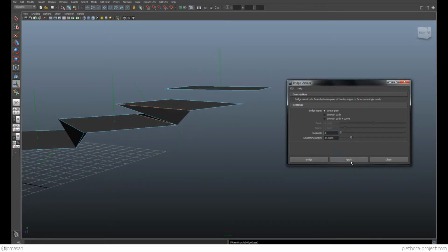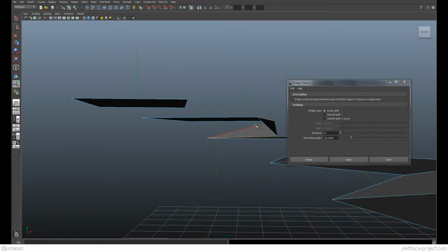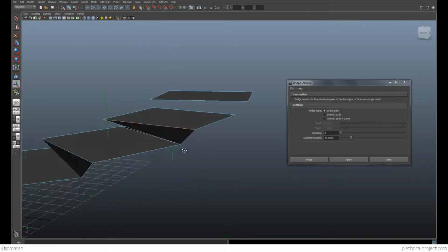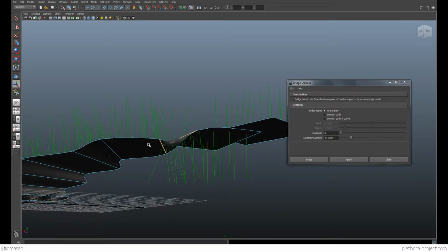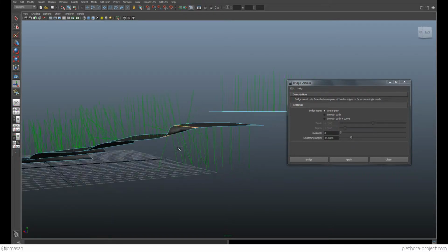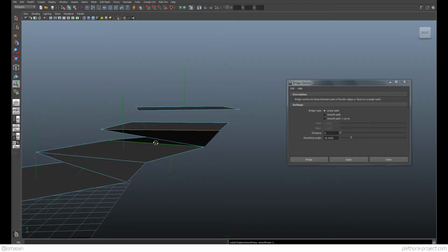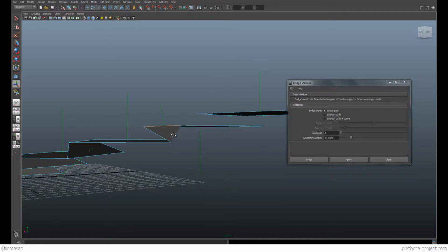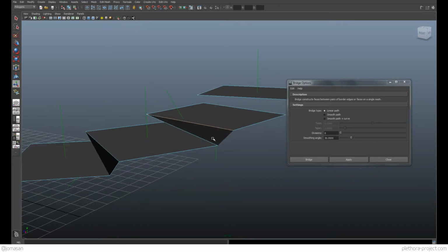So if you do this now, you can see that this point has been connected over there, and this point has been connected over here. If we smooth it out, you see, technically it's trying to fix this, trying to connect the faces the way they go, but that's maybe not what you're looking for, right? So if you get this problem, just check your normals. It might be exactly what's producing the problem.